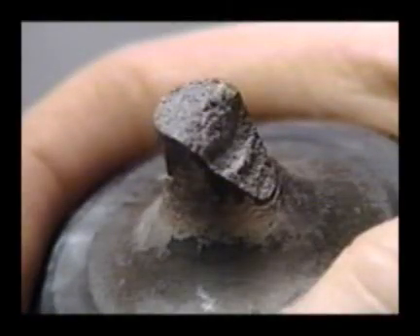Looking closely at this fractured bolt, we see a rough surface, gray color, very little plastic deformation, and almost no sparkle. These facts tell us that this is primarily a brittle intergranular fracture. This valve stem fracture is rough, has a gray color, does not sparkle, and shows no deformation. Under higher magnification, we can see how this fracture has followed the grain boundaries, exposing irregular grain surfaces. These irregular surfaces do not reflect light or sparkle, telling us this is an intergranular brittle fracture.